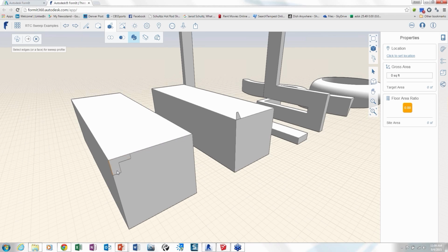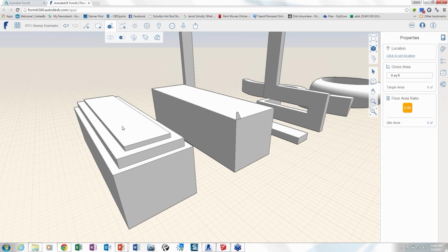And then this is cool, too. So here we're thinking add. In this methodology, we're thinking subtract. So we grab the sweep, we pick on this. Again, I'm going to use my little trick. So I pick on the surface, and it wraps it all the way around, which is kind of cool. So think out of the box with the sweep tool. I think most of us are thinking addition, addition, addition, because thinking like Revit, you have to always do a void to subtract. So here the tool just magically does both. So we got to think about that.